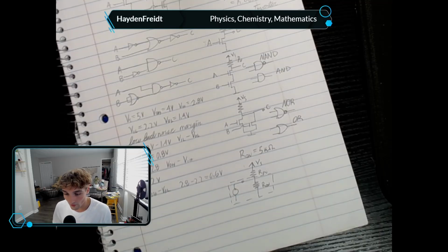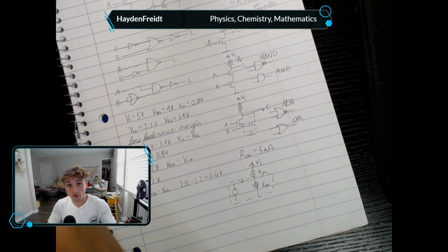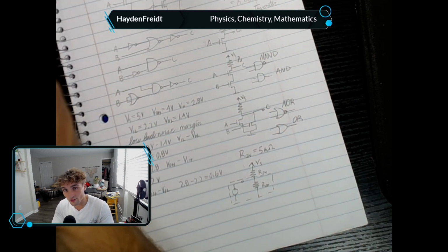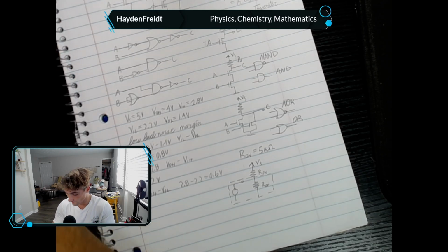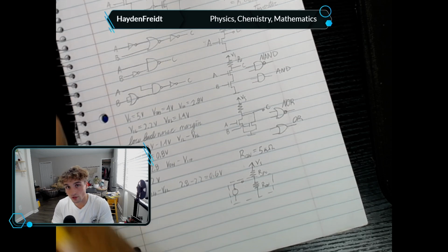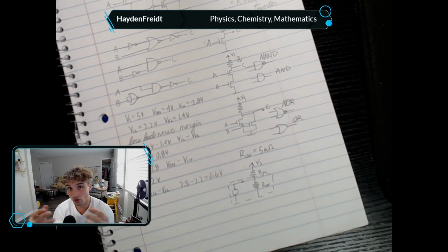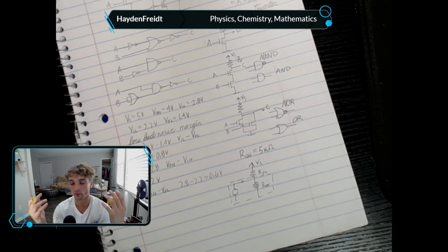If the transistor was off, meaning the gate source voltage was not above the threshold voltage defined by the physical properties of the transistor, then the switch resistor model for the transistor would look like R off, equivalent to a magnitude of resistance within the mega ohms. Okay, mega ohms. That means it has an incredibly high resistance and barely any current is passing from drain to source.